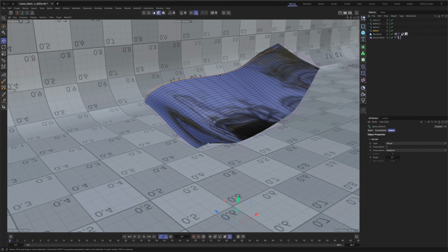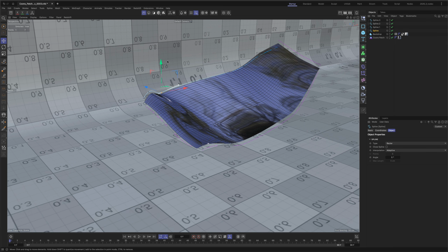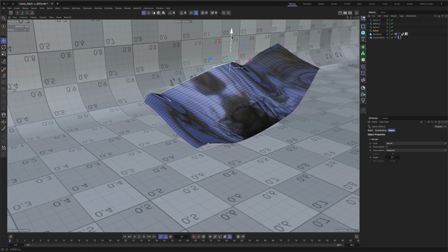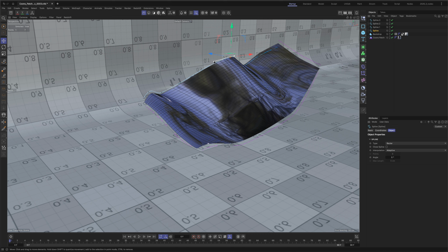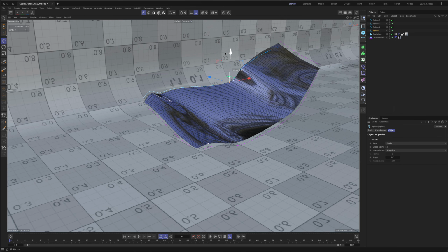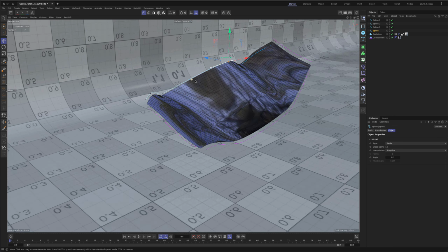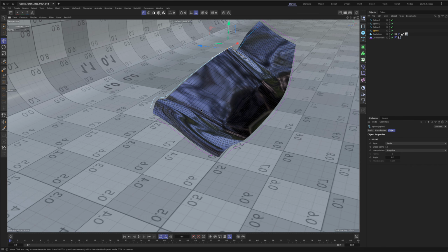You can select another spline, maybe select a different spline point and create, I don't know, a different shape. The shape will always conform to the point position itself and to the interpolation that is defined by the tangent itself. Now, what is interesting is that you can use blending. Let's go back to this mode, select this spline, and create a little bit more distance between these two.